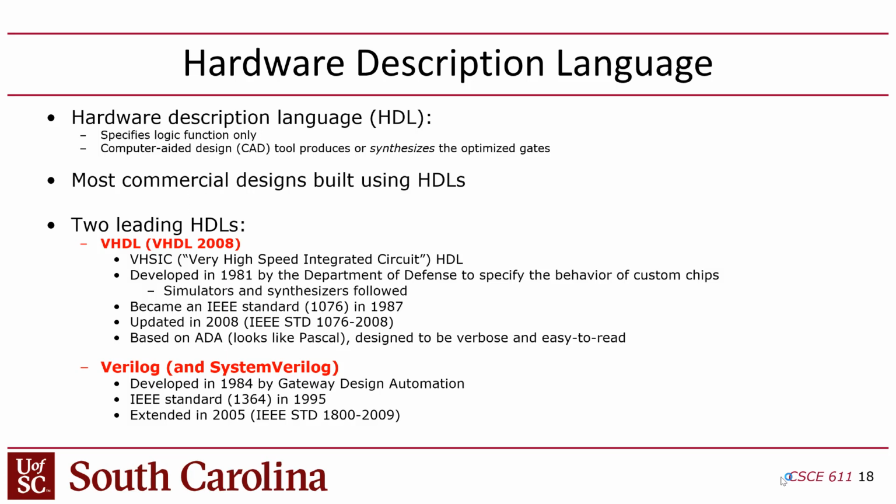In this class, we're going to use those tools. They come from two different companies. We're going to use a simulator called ModelSim, and a synthesis tool called Quartus. Two different companies, and they both use slightly different dialects of Verilog. So you may get an error when you compile with ModelSim, and then you go to synthesize it, and all of a sudden it's complaining about something. You're like, what the heck? I worked with the other. So just be aware of that.